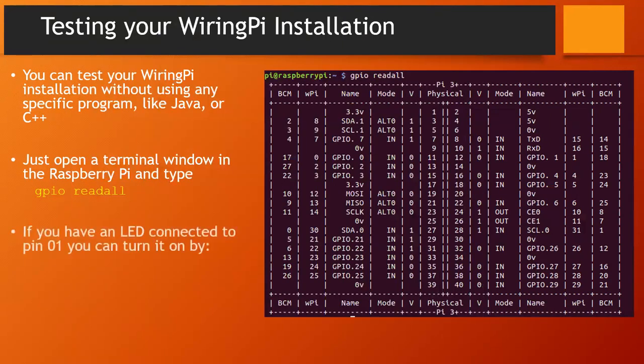Another thing that you might need to do, because I made that mistake when I was trying to make my example program later on in the next video: I wasn't able to turn the LED on. So I thought it could be a problem with my program, but it also could be a problem with the hardware, like the wires, whether the current is flowing in the right direction and not the wrong direction for an LED, and things like that.